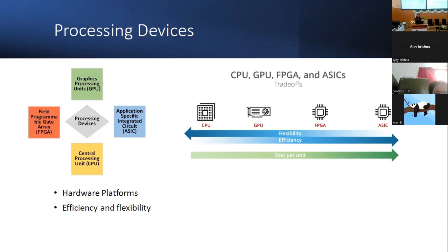So in research and academia, we can use this hardware. Why? Because it is not pre-configured. It has all the hardware units, that means it has logic elements like flip-flops, multiplexers, interconnections. The thing is, it has all the hardware units, but it is not interconnected. What does it mean? Whatever algorithm you want, we can make the algorithm as a hardware. In future, if you want to implement something else, you can reconfigure it. You can change the connections and a new hardware will be formed.